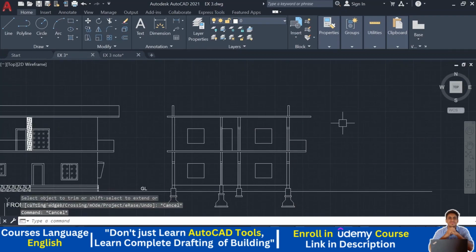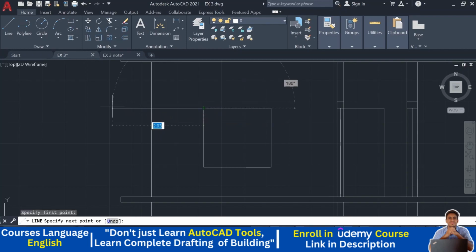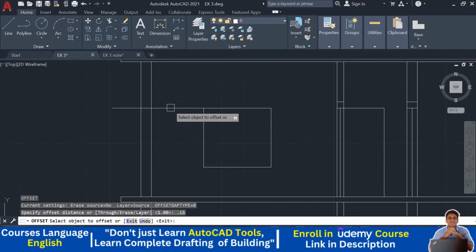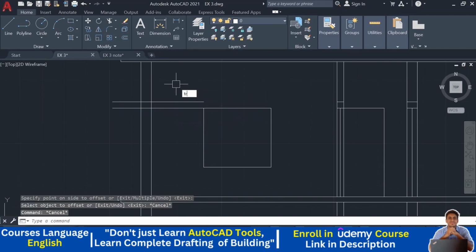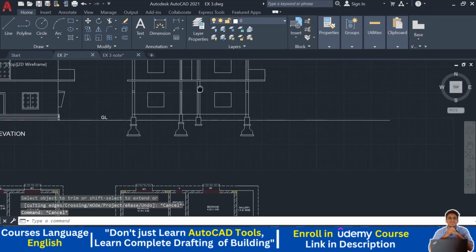Okay, so like this we need to show the first floor. We have not shown the lintel here. I just show the lintel, offset 0.15 is the thickness of the lintel. I just show this one and I just trim. Okay, so I just go to the plan.